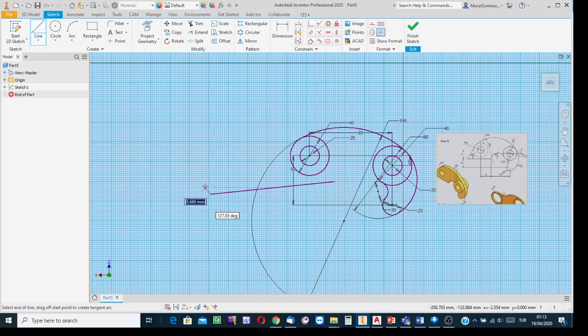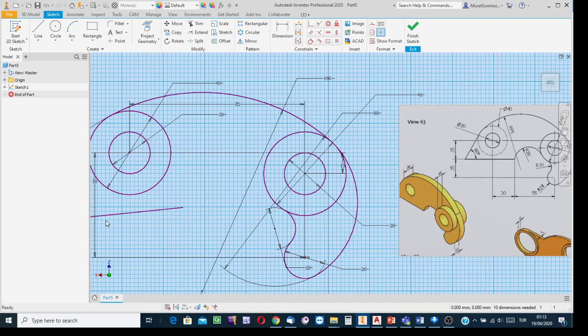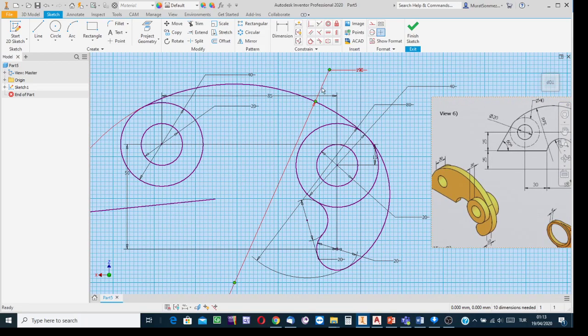Okay. If you have a dotted line between the cursor and a certain characteristic point, escape from that positioning by moving the cursor a little bit. And then, well, I know that this line is horizontal. Input the horizontality constraint, click on this and then apply, indicating the line. Now it is perfectly horizontal. And bring this terminal point to the correct location, for which the coordinates are 30 by 25.